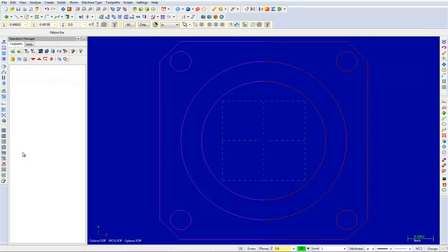When performing a transform function, XForm, Mastercam creates a temporary group from the originals, red, and a result, being the purple, from the transformed entities. However, they stay in effect only until you use the Screen Clear Colors function or perform another transform function. That being said, select the clear color icon as shown. Your geometry has now been returned to its original color.